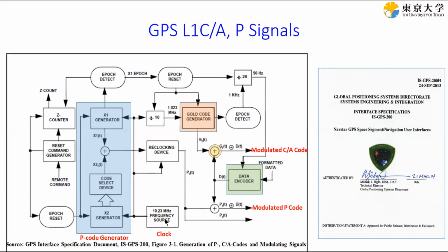So that's the reason GPS time from the GPS signal is used as a reference time for many systems, okay? Because the GPS clock is extremely accurate because it's generated using the atomic clocks. And this 10.23 is the base frequency. And this 10.23 megahertz is either amplified or divided to generate the necessary signals here. Okay? So this is the hardware approach.